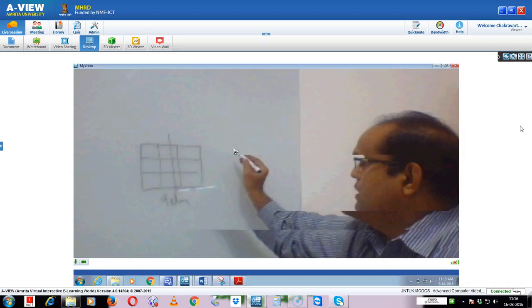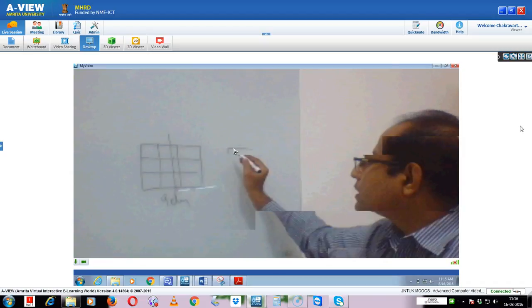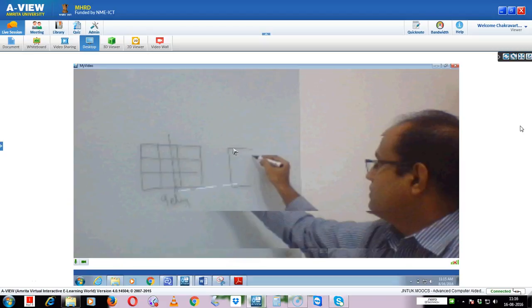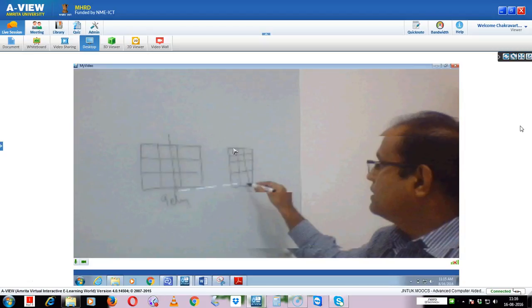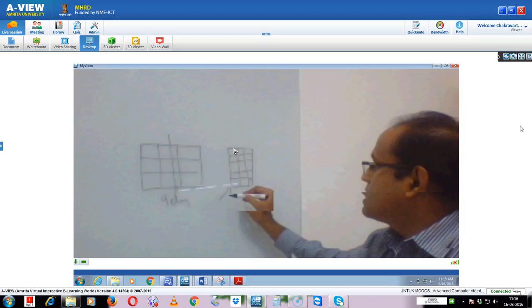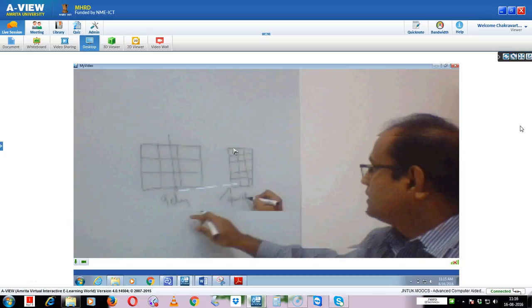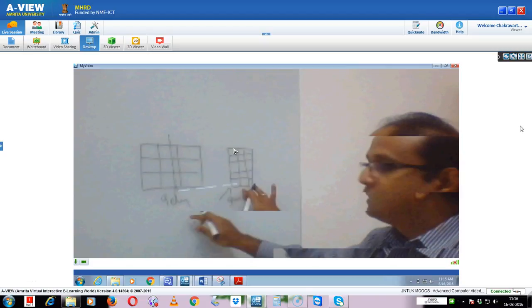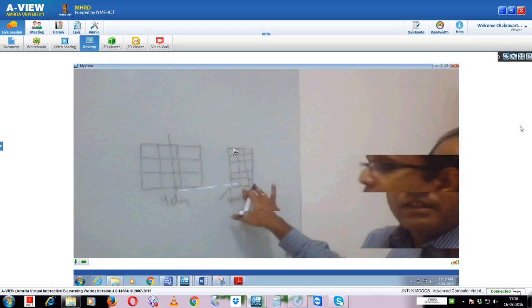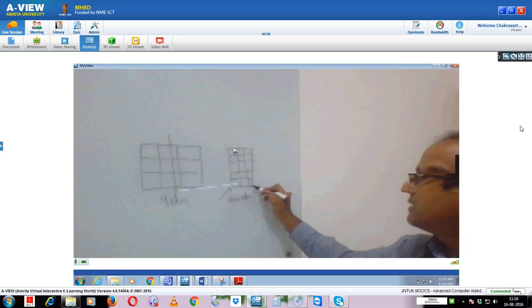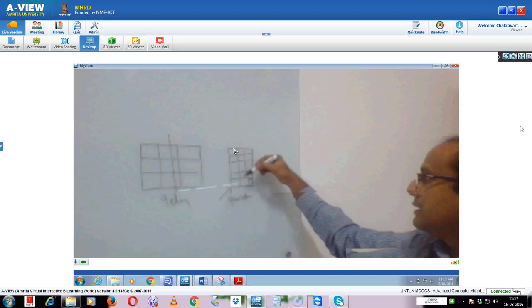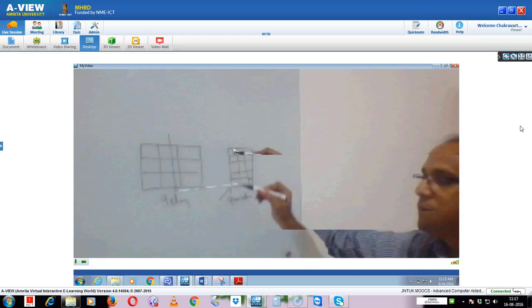Same model, if I take symmetry, instead of 3 elements, I can put more elements. So this will have quicker convergence. I have put more elements and I'll get better accuracy in the model. At the same time it will have better convergence because I put more elements here and I can capture the geometry.